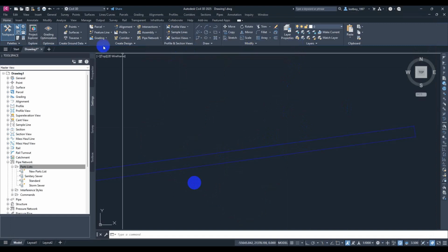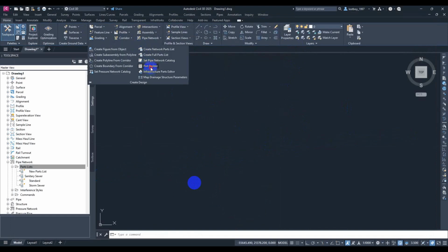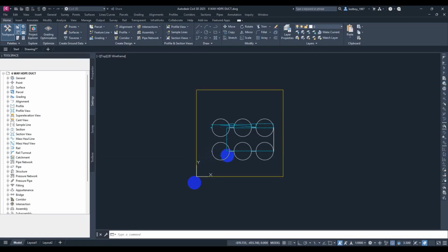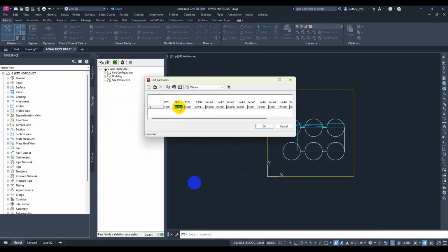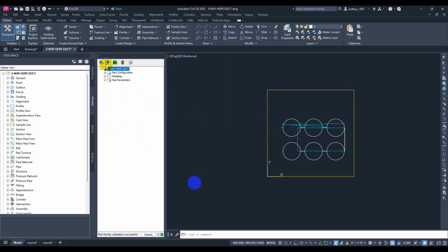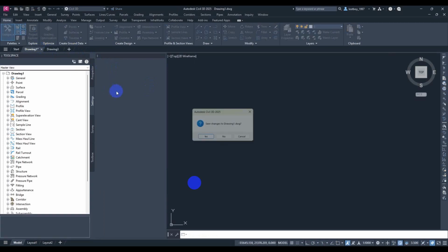So you will go back and change this to be normal, or the values that I want, from edit sizes, size value or edit values, okay? BIH I'll make 150, BIW I will make it 60 or 40. This is the spaces between, and wall thickness is 1 millimeter. BIH represents the pipe diameter, BIW represents the space between the pipes, and wall thickness is this thin part that ties all the pipes together.